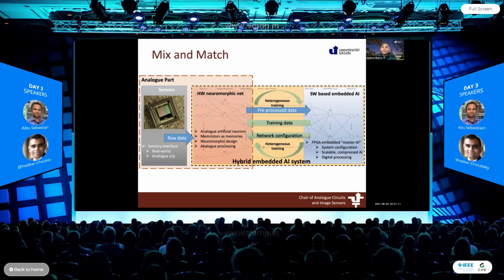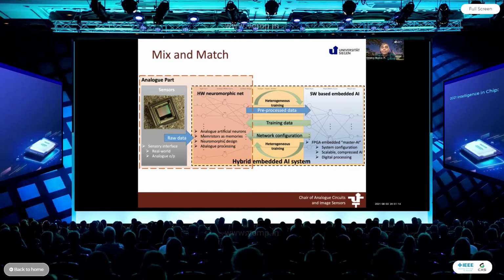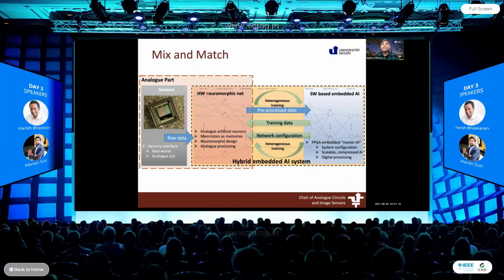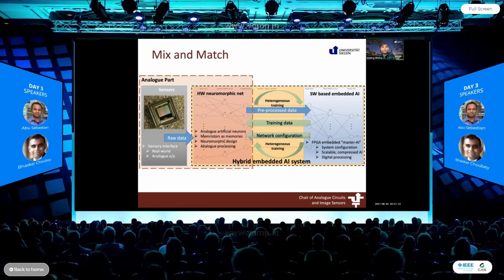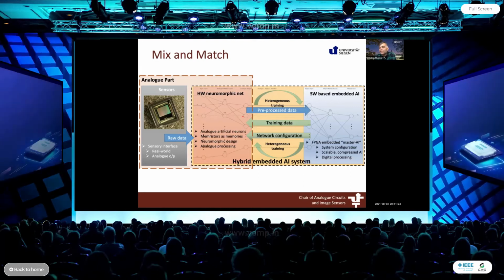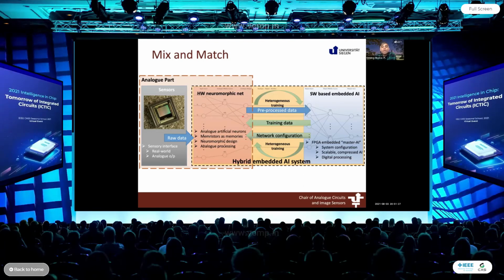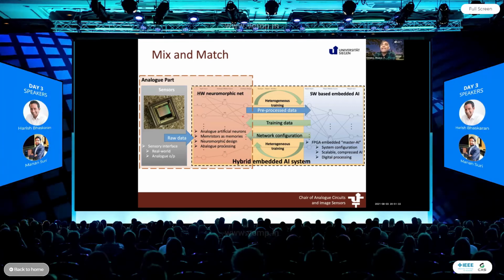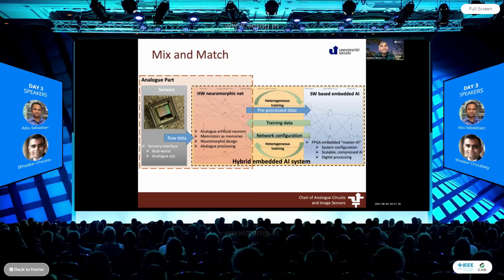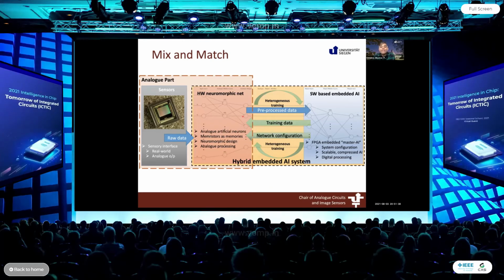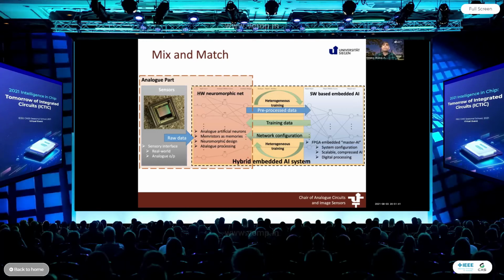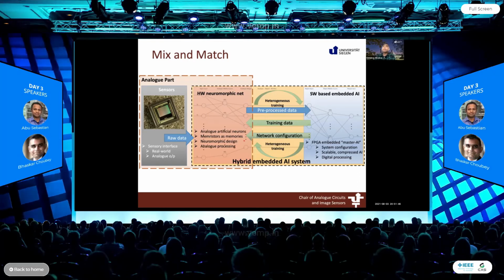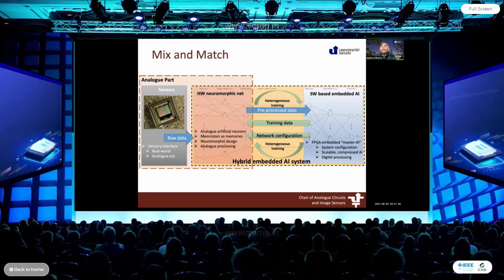One also has to think about, if we transform the analog to digital here, what is the cost of digitization? Are we going to compress the input data to a smaller data set? Right now I'm showing a neural network which is compressing the input data set. That would be perfectly fine, but would we actually be able to compress it after a layer or two? If you're just having CNN type neural networks, you would most probably be compressing. But depending upon which neural network, you might actually end up with a larger number of points here, which then would require more ADCs. Or you might end up with a large number of points here, but whose resolution is not the same resolution required for an imager.